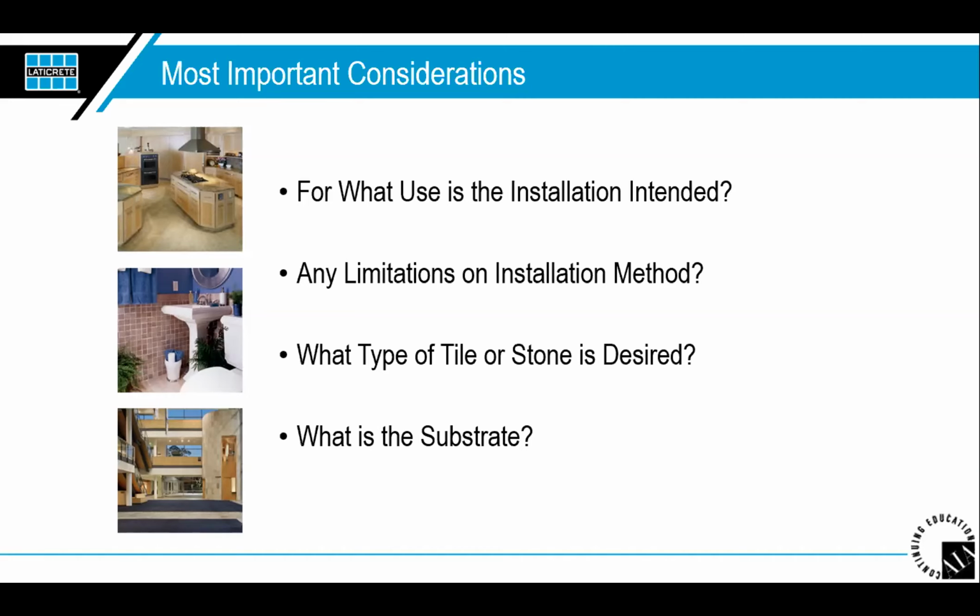But the substrate is definitely one of the most critical factors. It must be sound, it must be clean, it must be suitable to receive a hard finish. That occurs quite often actually on my side of the fence, where we have multiple jobs where the substrate was never originally built to withstand the tile installation, the weight of the tile installation. I was actually just a part of one.